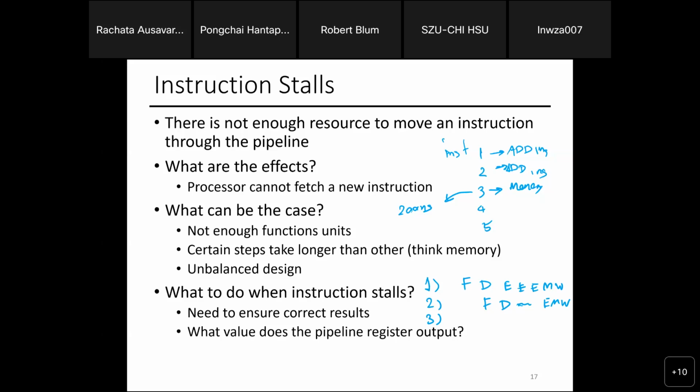The bug is, if I have to do the chip design for the first time, I will miss the write signal at the cycle I have to do. Imagine everything has to be cycle accurate. If I'm not doing it cycle accurate, it means that I write to the wrong guy, right? So you shift the write signal by 1 clock cycle, everything goes kaboom. It's like, where is this thing going wrong? So you can imagine that happening.